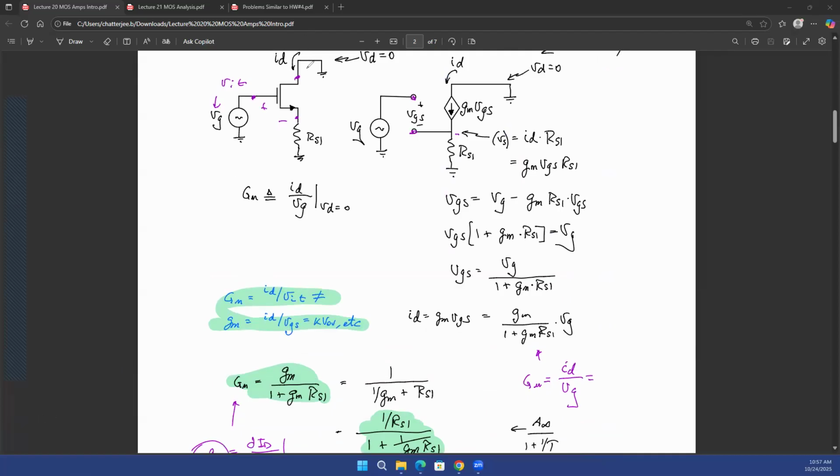this will give you better stability in the circuit in terms of the gain. Why? Remember that this is a MOSFET, and MOSFETs can have process variation. For example, you buy a MOSFET from the market and he buys a MOSFET from the market, and they can have different threshold voltages. Even though in the data sheet they might say that the threshold voltage of the MOSFET is 0.7 volts, you might see 0.65 and he might see 0.75. Right? That's always possible. And that is called the process variation or the manufacturing variation.